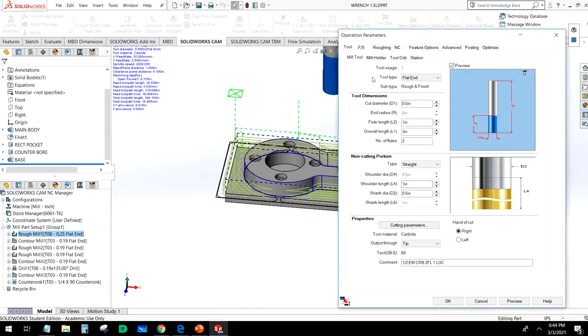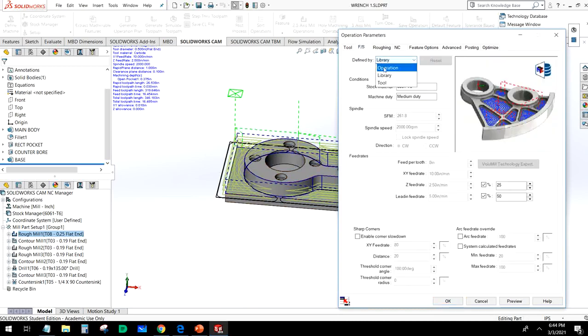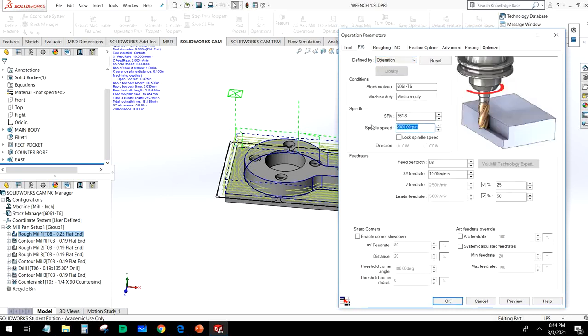So we bump up that tool thickness. For feeds and speeds, our spindle speed when we do the calculations out, and remember that is 4 times V, our surface speed is V, and for high-speed steel cutting in aluminum, that is a value of 300. So 4 times 300 divided by our cutter diameter, which is 0.5. And when we do that math, we're going to get a spindle speed of 2400.